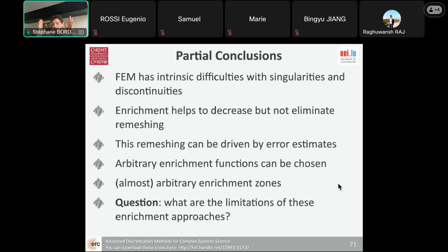So that just assumed that everything is linear elastic. It means that the cracks are supposed to be relatively small with respect to the whole structure. It means that the whole structure remains elastic. If I load the structure and unload it, it comes back exactly where it was. There is no such thing as residual deformations, so you do not have a deformation which lingers after unloading. If you took a rubber band and elongated it only a little bit, and let it go back, it would come back to its original position.